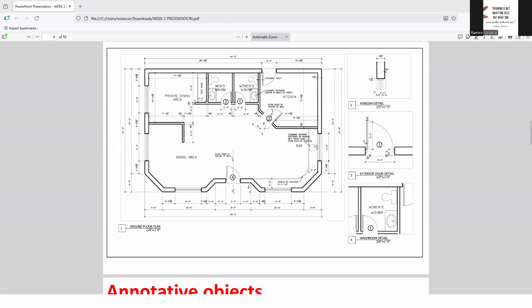Mm-hmm. I have a quick question. It's for the dimensions. I want to have it 27-0 inches, because this is how it is there. Yeah, so you go to dimensions tab, units first. Make sure you're showing the precision. That's for the angle, I think. This one, 1/16 or 1/32. Yeah, let's make it point something or 2 decimal. Oh, yeah. Okay. Click OK.